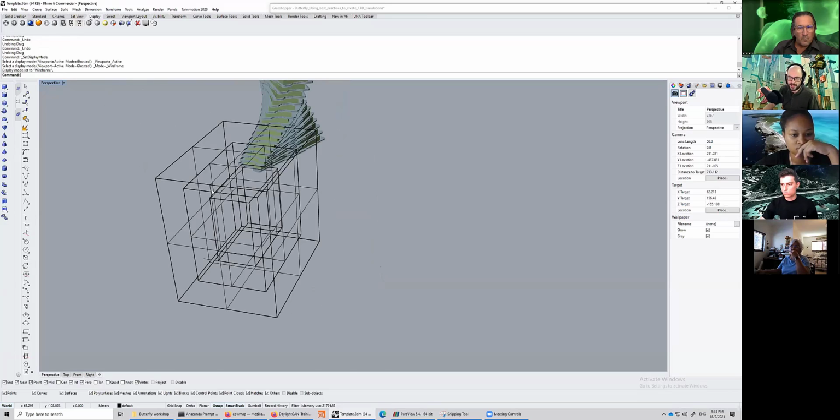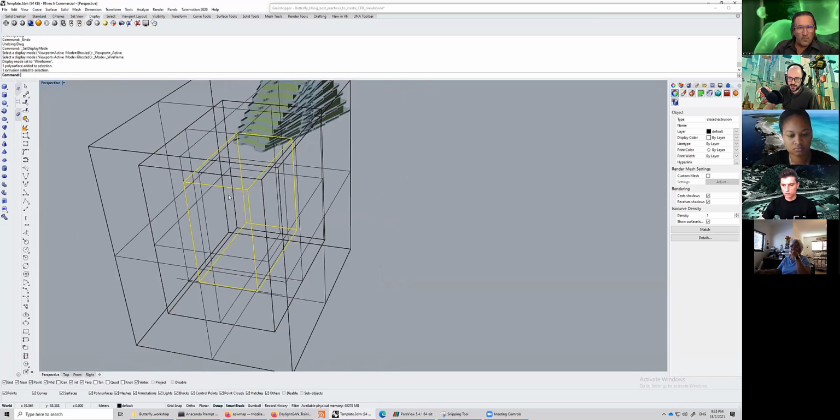So essentially what you're doing is you're taking your geometry here, and you're making these volumes. And inside those volumes, you sequentially refine less and less and less. And this is very important because you want your meshing to be a gradient mesh. You want the jumps from one area to the other to not be very big. And this was a big problem when Butterfly first came out, before we made the component that I will show you later. People had, let's say, 1 meter mesh around the buildings, 10-meter mesh directly after, and then everything would diverge, nothing would run properly. So this logic of doing it in a stepwise manner keeps things correct.